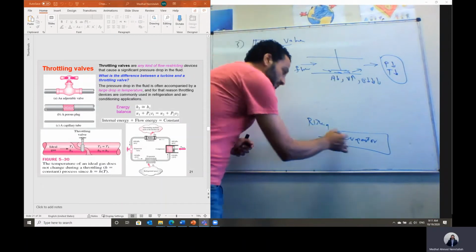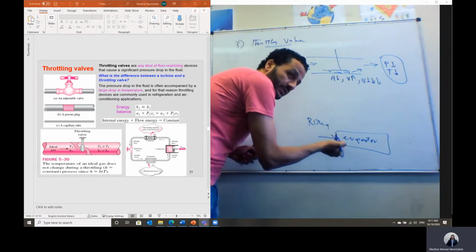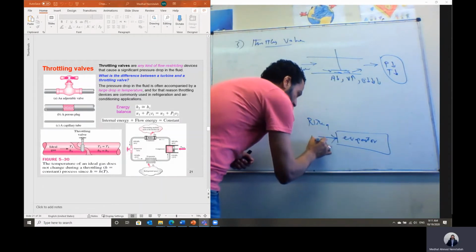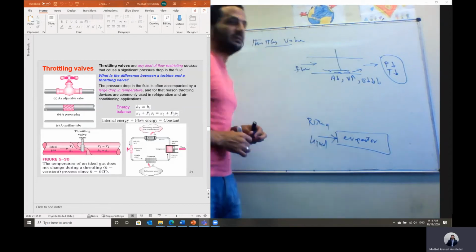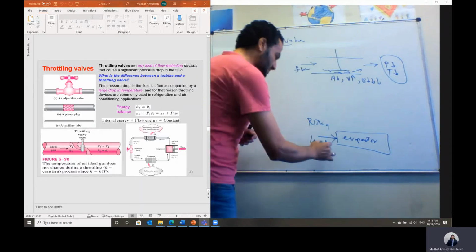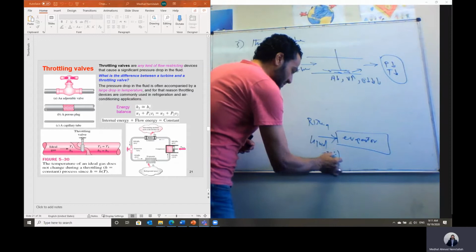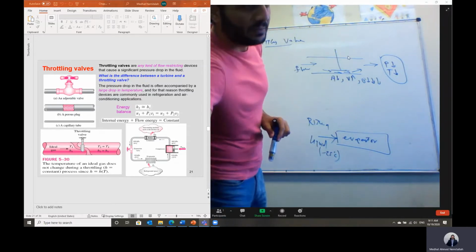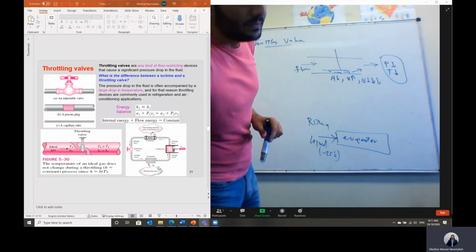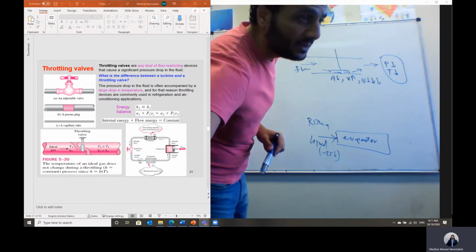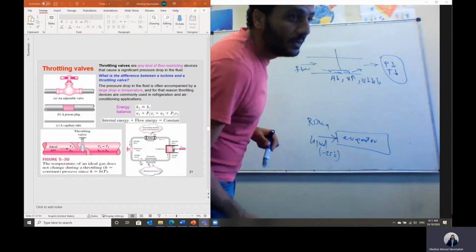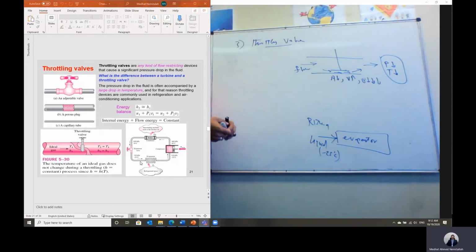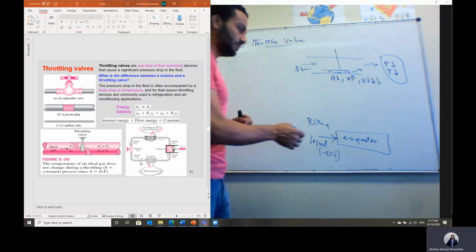In this case, this freon is coming to the evaporator or the freezer of your fridge in the liquid form. Usually its temperature is about minus 25 degrees C or something. You can look here, these are some numbers. This is the evaporator, the flow is coming at minus 25 degrees C and 120 kilopascal. Coming to the evaporator, what happens inside the evaporator or the freezer?